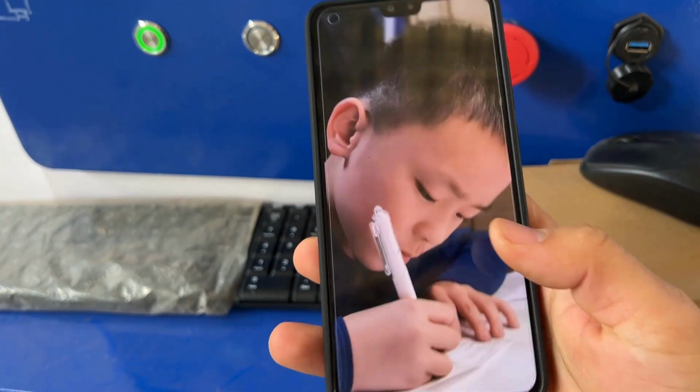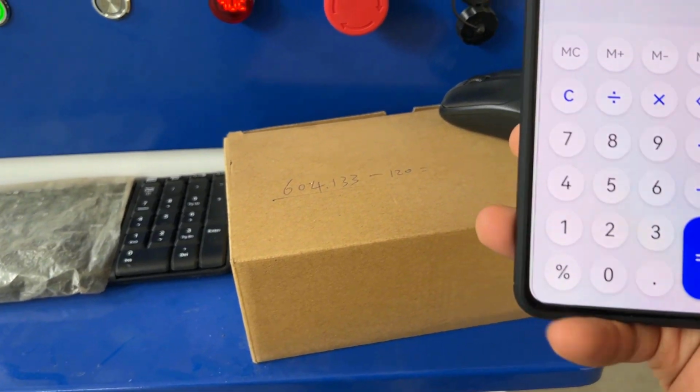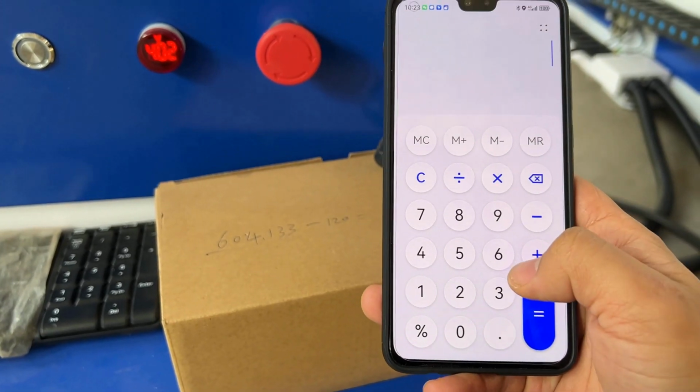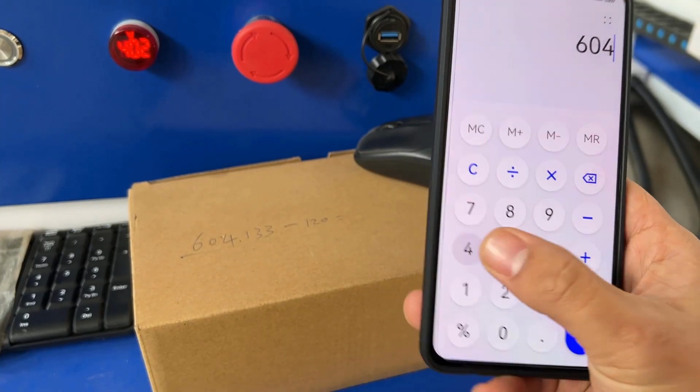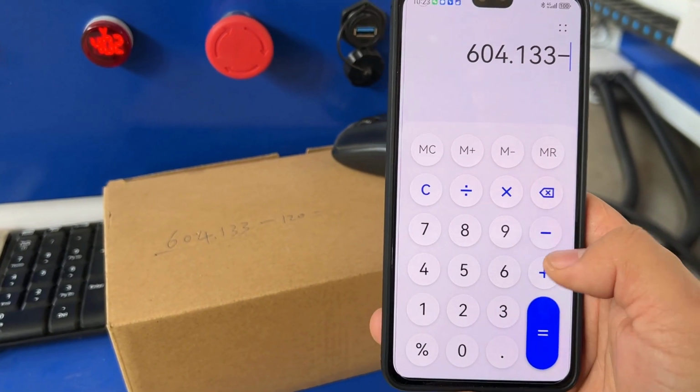The data obtained is the distance between the spindle rotation center at +90 degrees and -90 degrees. Half of this number is the distance from the spindle rotation center to the bottom surface of the spindle.